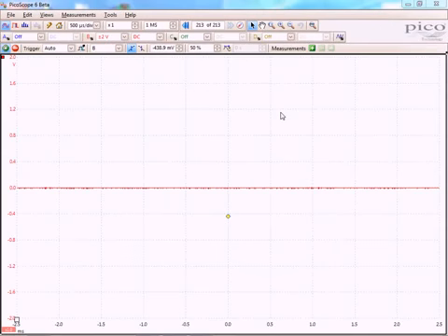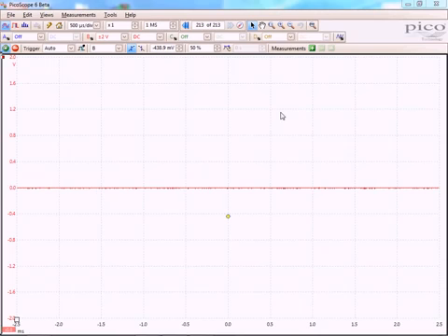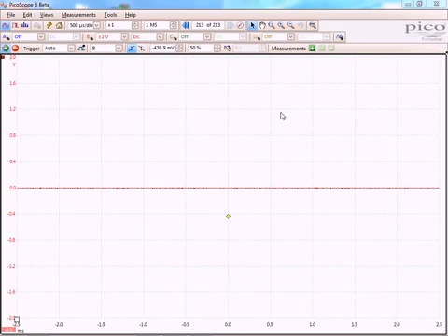The next feature I would like to discuss are the fantastic new improvements to the signal generator functionality. For those of you who are current PicoScope 6 users, you will be aware that the vast majority of our products have a signal generator incorporated as part of their functionality. The signal generator can be used to output waveforms at a fixed frequency. It can also be used as a more advanced source by using the frequency sweep options. Today we are going to focus on the new signal generator trigger options. These options allow the signal generator trigger to output one or more waveform cycles in response to a trigger condition.